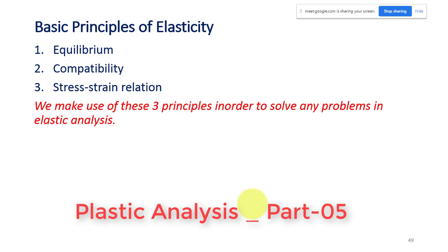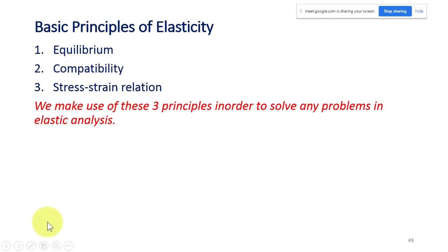Usually, if your problems are statically determinate, I can find out all the forces and all the reactions from the equilibrium equations, and then we will be using the force-displacement relation to get the displacement, and that is your stress-strain relation. And if your problem is statically indeterminate, then we have to use your compatibility equation. So basically, we have three principles: equilibrium, compatibility, and stress-strain relation to solve any problems in the elastic analysis.